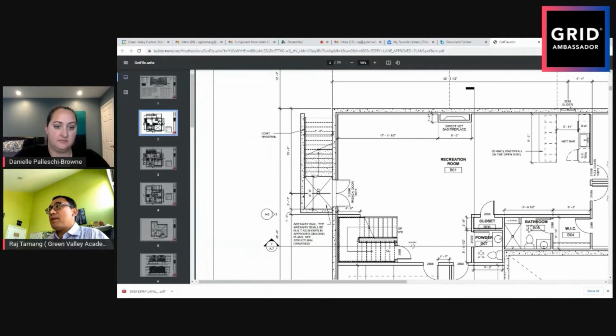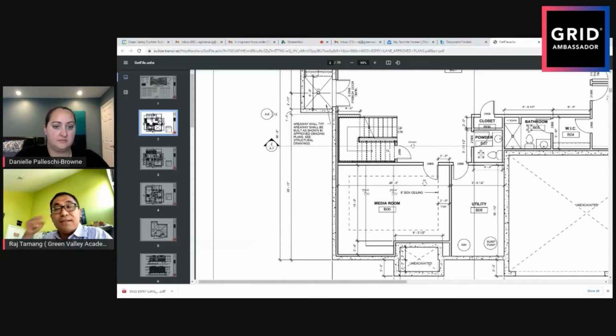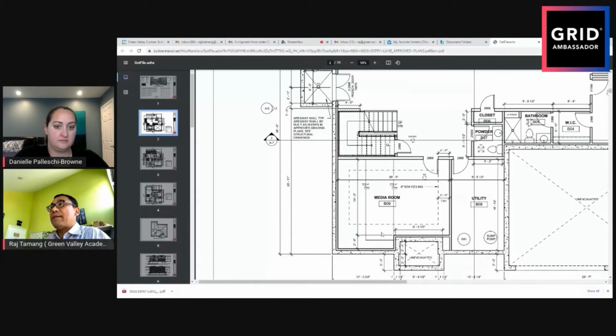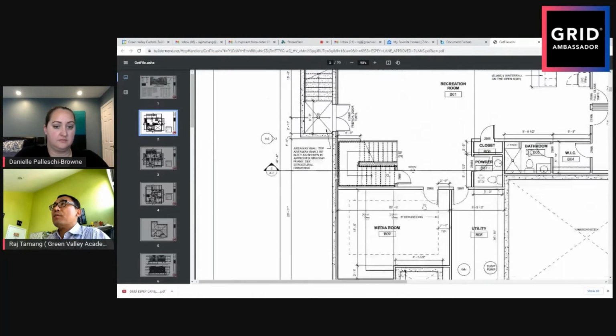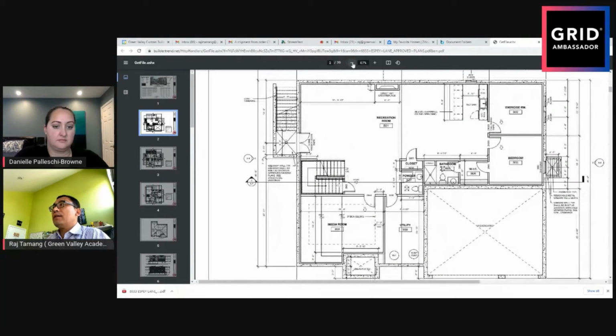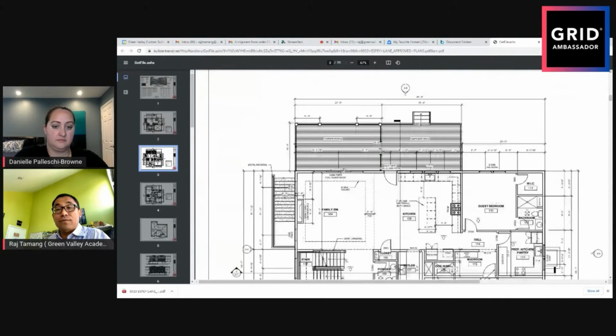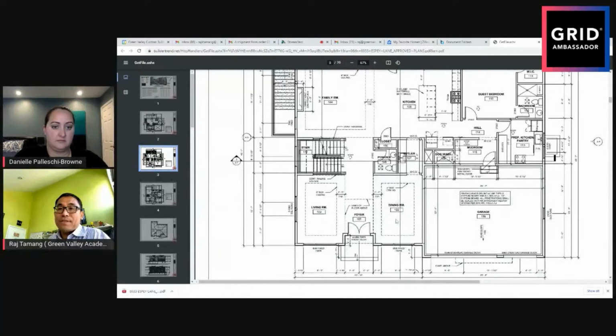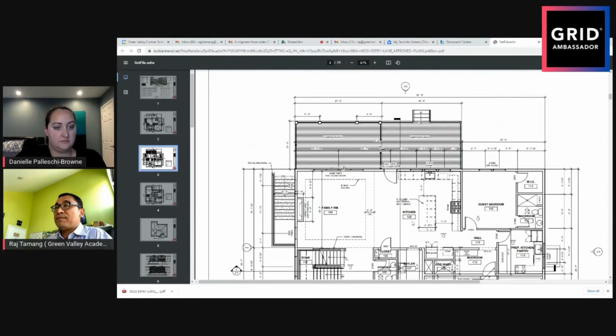Also remember, since this is a fully buried basement, this is all concrete wall. The way you see it in the floor plans, the thickness and hatching is different versus a stud wall. This is a 2x6 outside. See the thickness and the hatching? It's different, because the first floor and second floor are stud wall, 2x6, 2x4. The basement is concrete.